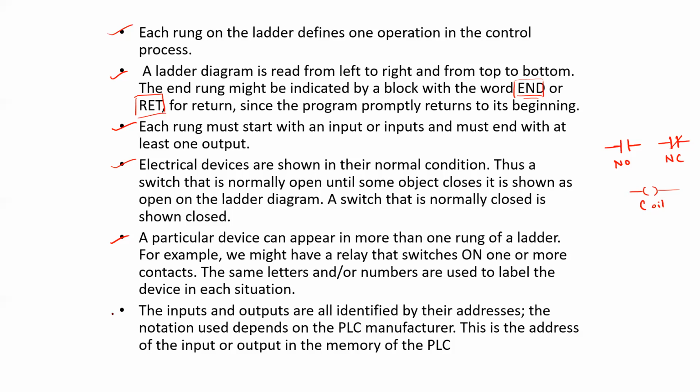And the inputs and outputs are actually identified in terms of their addresses. So depending upon the address of the port at which a particular input or output device is connected, the input and output devices are designated while drawing the diagram. And normally the notation of the addresses is different for different manufacturers.